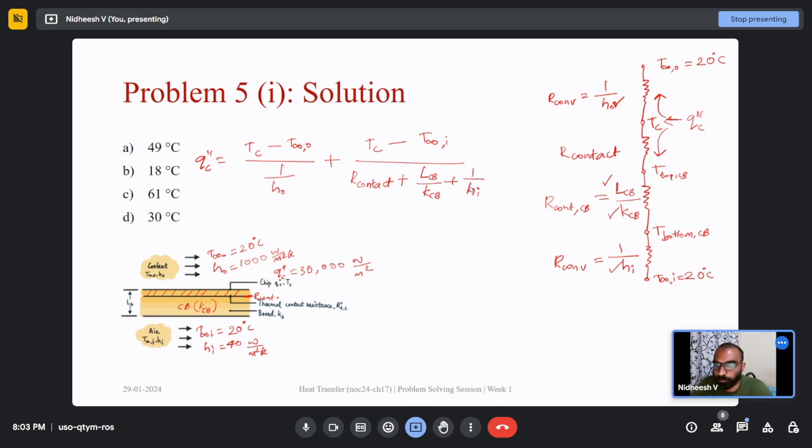Is it clear for everyone how we wrote this equation? Whatever heat flux is coming is going in two ways, through the top side and bottom side, and just like how we add up the current in an electrical circuit, we can add up the flux that is being divided into different directions. It's clear, right?